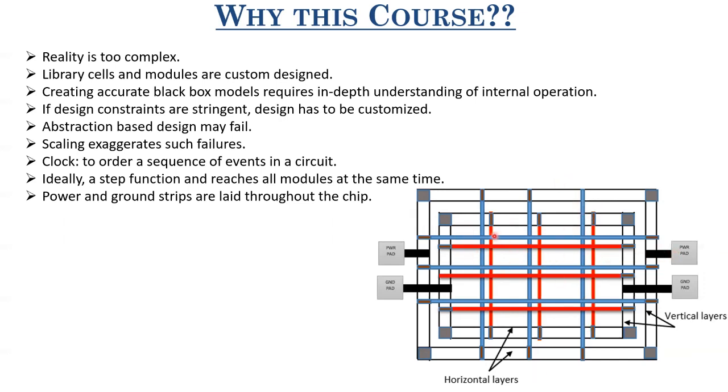And as such, if they have independent connections to these VDD lines, they don't have to traverse a larger distance in order to get VDD or ground. Only when you have to traverse a larger distance on the interconnect will these resistances or parasitic inductances come into the picture and reduce your supply voltage as compared to what you have exactly given to the supply.